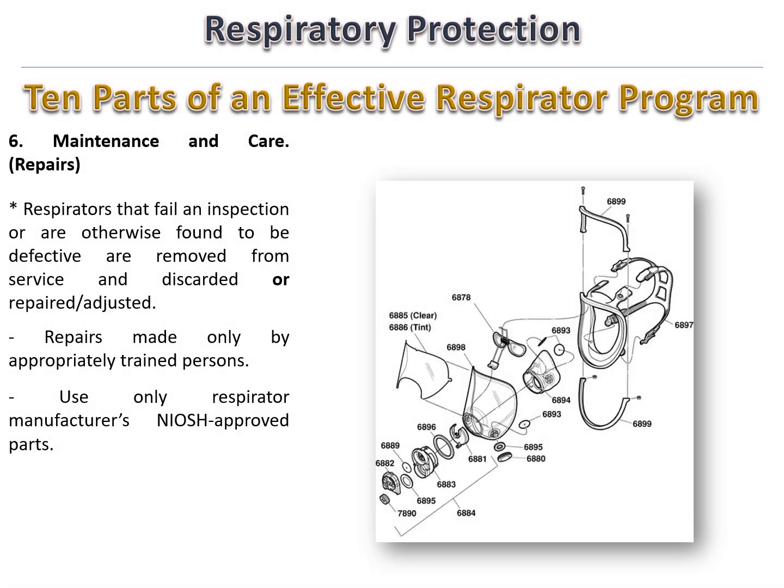6. Maintenance and care. Repairs. Respirators that fail an inspection or are otherwise found to be defective are removed from service and discarded or repaired/adjusted. Repairs made only by appropriately trained persons. Use only the respirator manufacturer's NIOSH-approved parts.